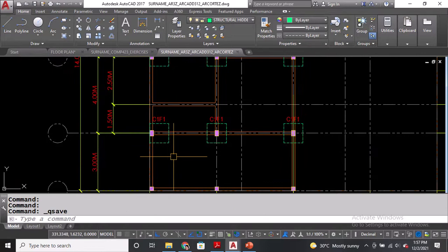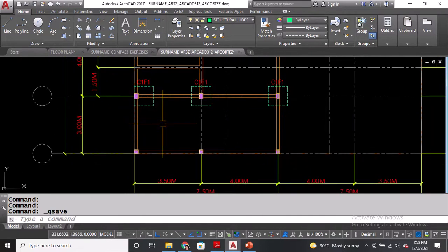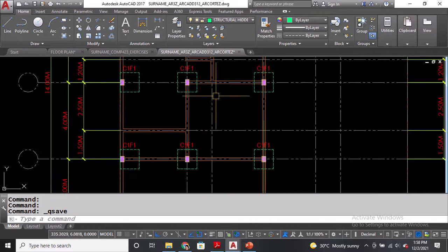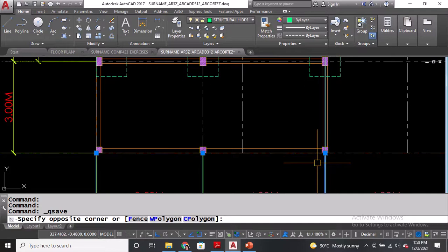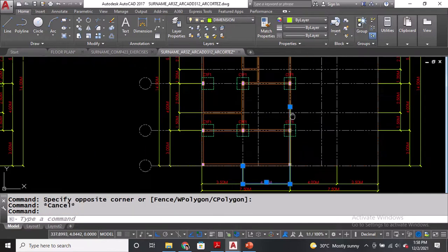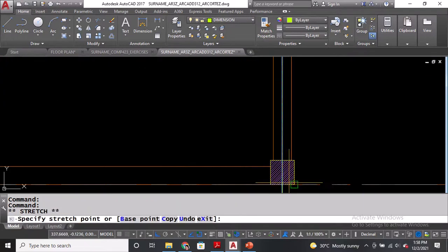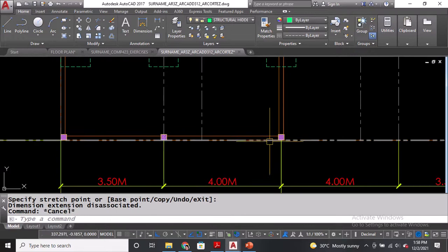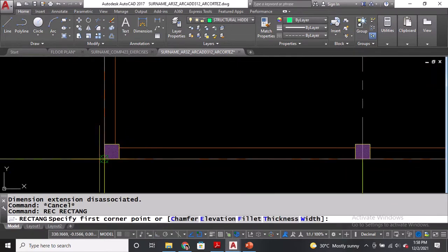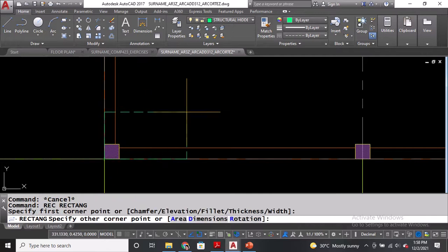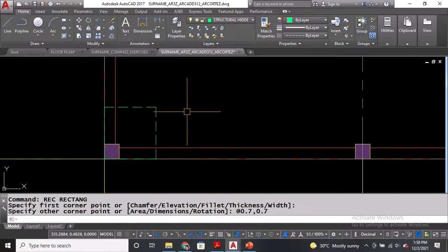Okay, after the C1F1, of course, yung reinforcement natin for the fence, they will be smaller as compared dun sa bahay. Kasi, yung bibit-bitin lang po niyan, or yung susuportahan lang po niyan, will just be the fence. Unlike yung sa bahay na meron pang roof beam, meron pang mga dead loads and live loads, and so on. Okay? So, we're going to create a rectangle. We're picking here dun sa sulok. That's at 0.7, 0.7. Enter. So, okay na to kasi pambakod lang naman siya.